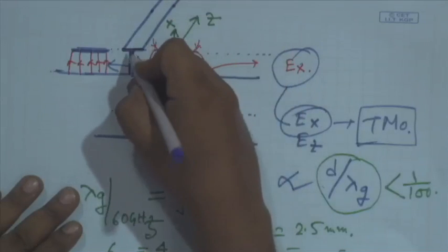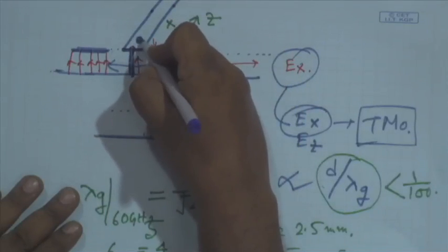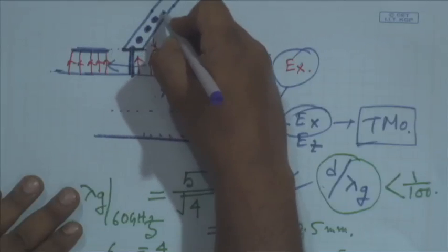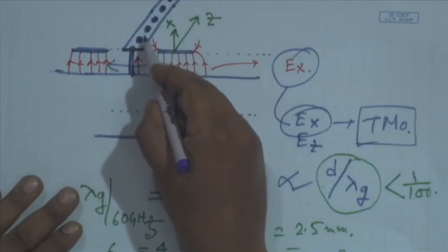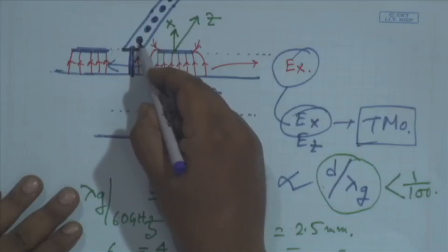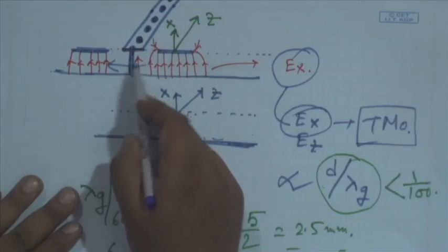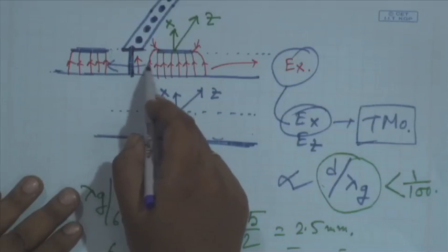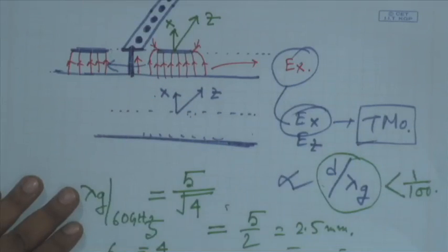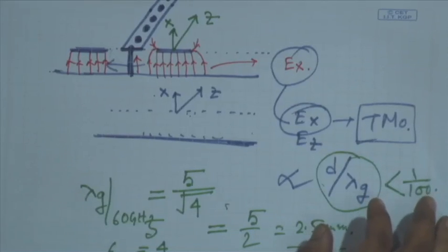In the z direction these vias will be periodic, and the separation we typically use is less than lambda g by 4 at the highest frequency of operation. It can suppress this coupling to some extent, let us say by 10 to 15 dB, but it can't avoid the effect completely. Okay, so let us take one break, then we will see the other parts.